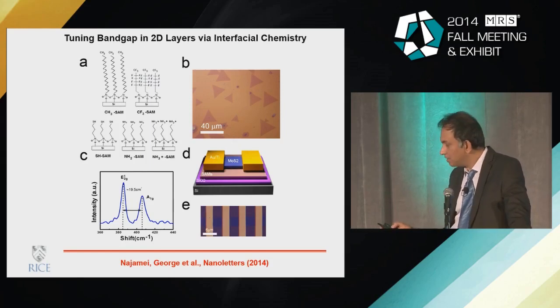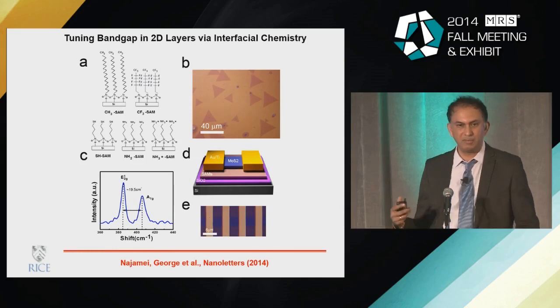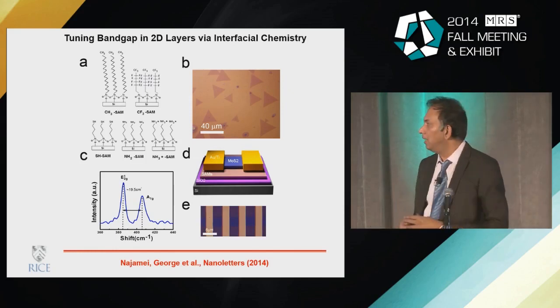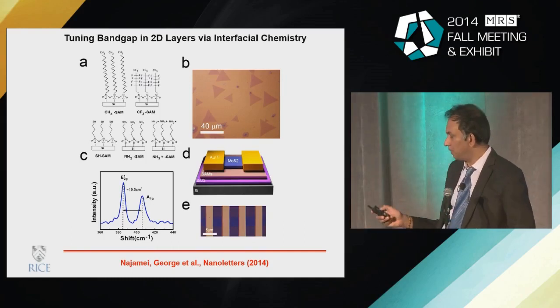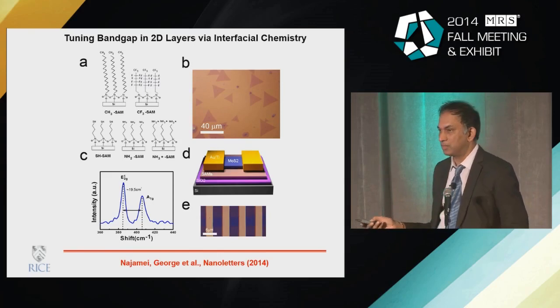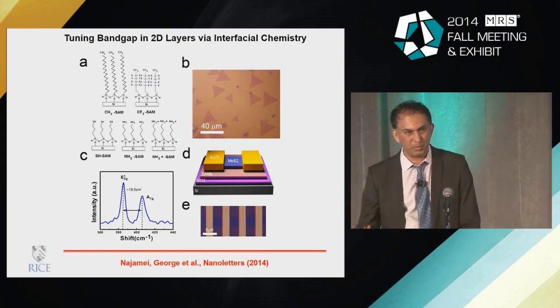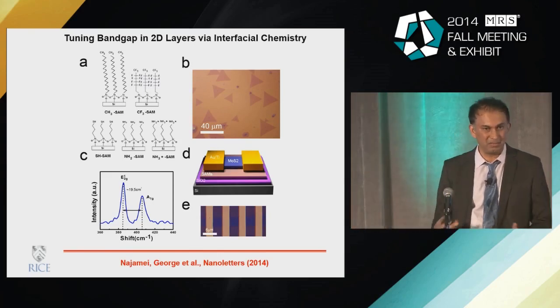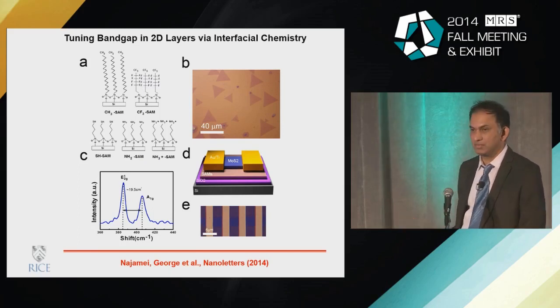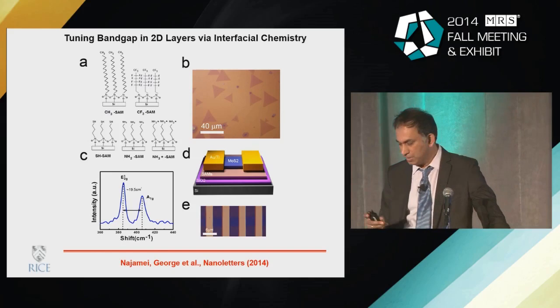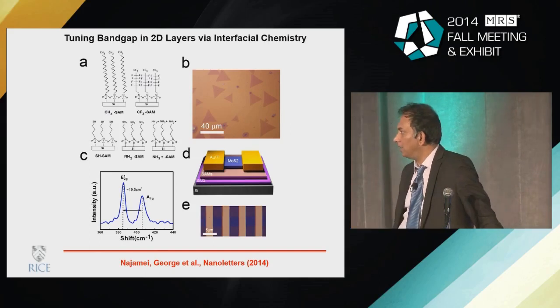And here is a demonstration where we are able to place the molybdenum sulfide on self-assembled monolayers, soft substrates. Depending on the terminations of these self-assembled monolayers, we can change the electronic character of this material. The transport behavior changes quite dramatically. The conductivity changes. The mobility changes. And that's partly because of this charge transfer between these terminal groups and the TMD layer.